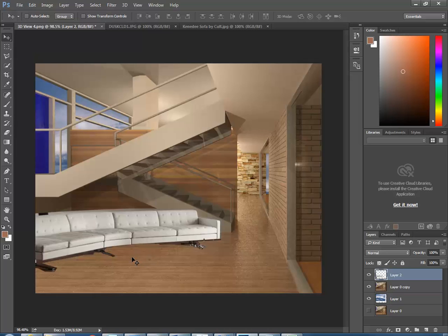And as you improve the stuff you've done with Revit, remember you can just replace the layers instead of doing all of this work again. You can keep the furniture and things you've put on top, and then just stick the layers in underneath that have the new rendering. So you don't need to have everything done perfectly in Revit to start doing this.